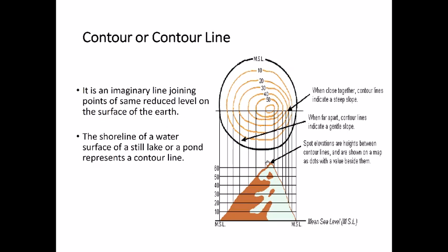Let's see over here. This picture represents it very accurately. Now we have a hill. If you take elevations along this part of the hill, you would draw this contour over here. Let's say this is for 60. All the points along this circumference along the hill, on all sides, make up a line of 60. Then if you do it over here, all the points along this are at 50, and see that the perimeter keeps on increasing because it's a conical shape, and at the top the perimeter is smallest. That's why this loop is not very wide, or the diameter is not too much.